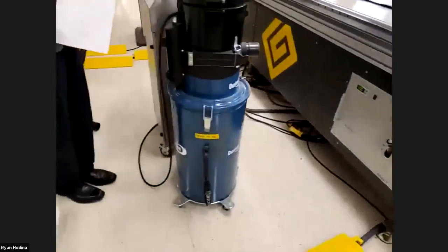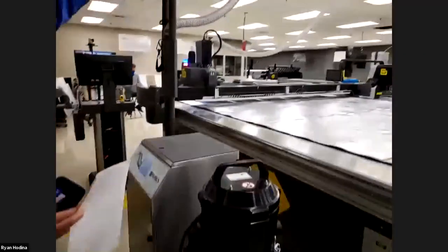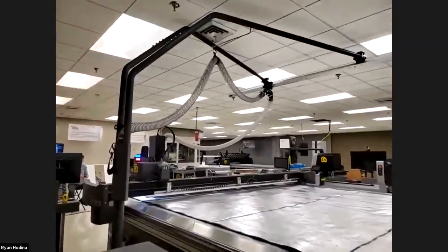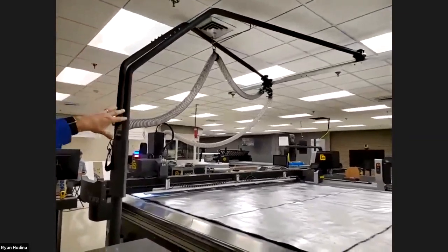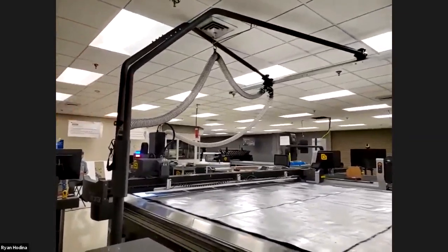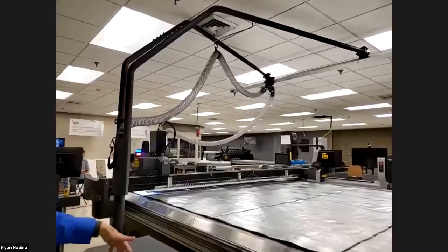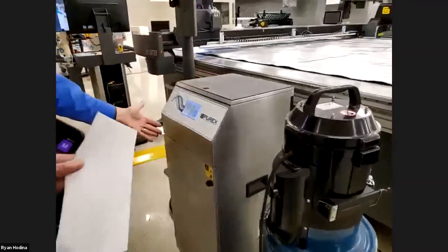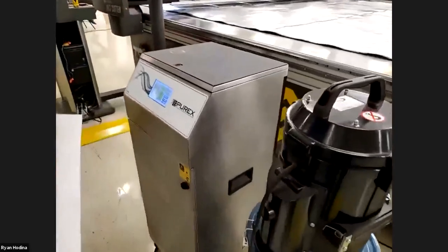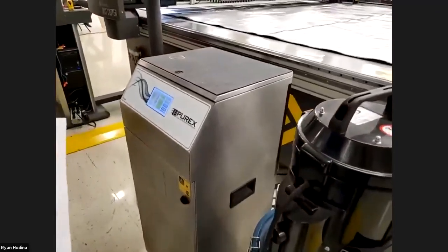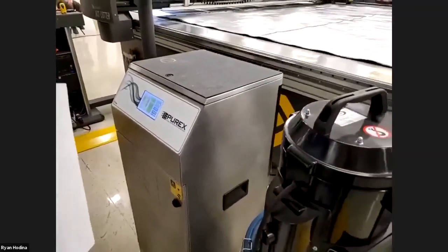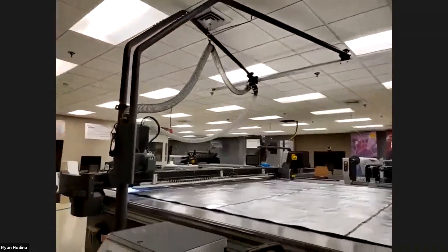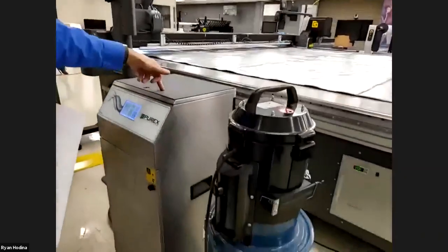And with the laser, you can see this device up here is called a festoon. That's the black apparatus with the hoses on it. And the purpose of that is to bring hoses from the cutting head in the case of the laser over to the fume extraction system. So the purpose of the fume extraction is when you're using a laser, you don't have to worry about venting anything outside. The smoke from the laser comes through these hoses over the festoon and into the purification system.